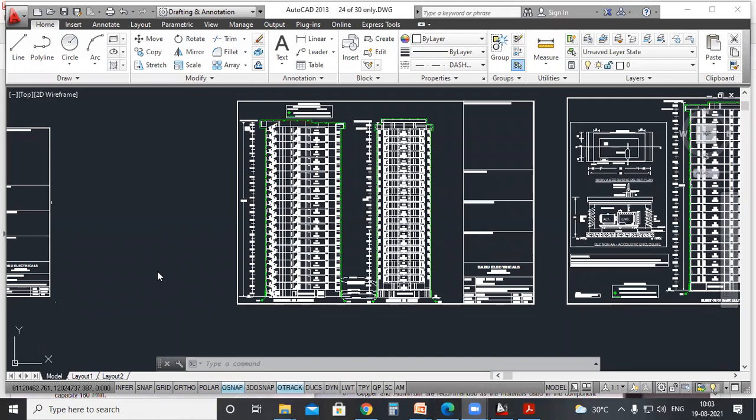Yesterday, we just started the portion on lightning arrestor, so we can continue the same. We were discussing the importance of lightning arrestor for a building, and today we will discuss the requirement of lightning arrestor, and how we can calculate what all things are required for the lightning protection system, like whether lightning protection is necessary or not. Based on the Indian standard, we'll be doing the calculation.